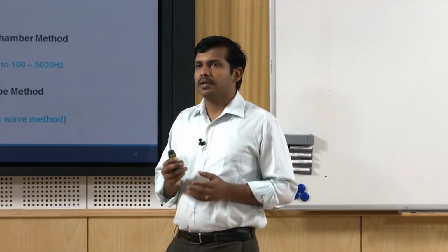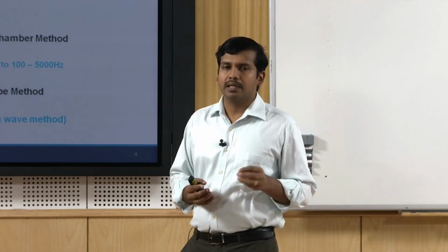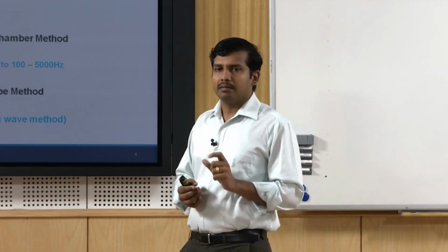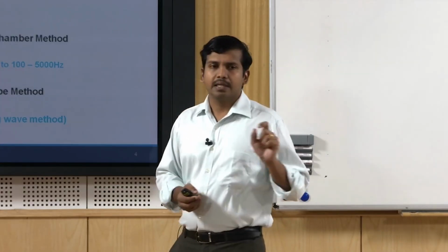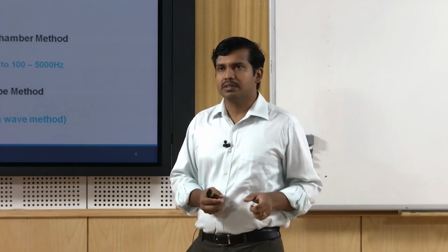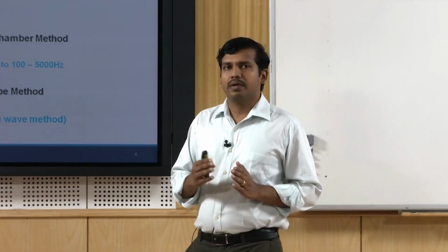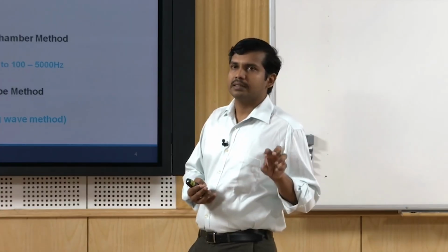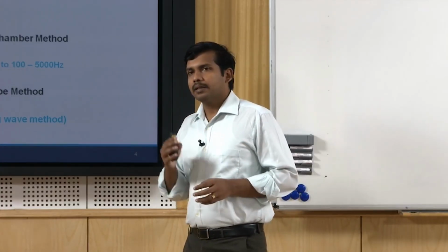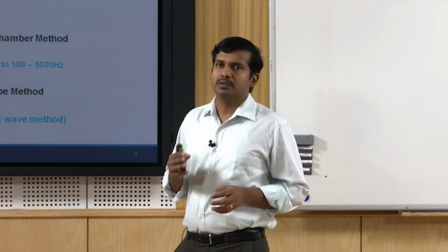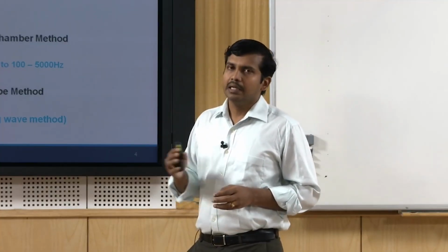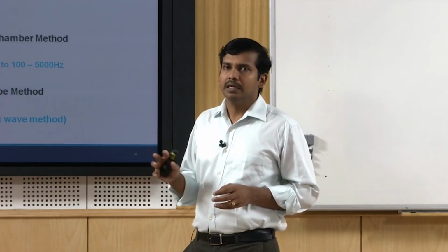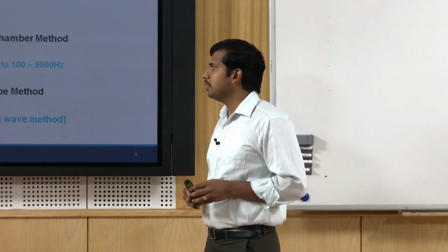So ideally when you select a material, if you want a real performance based selection, it is rather better to look at at least 3 specific absorption coefficients, that is absorption in the low frequency, something around 63 or 125 hertz or sometimes 250 hertz. Better is to look at 63 and 125 hertz. Then in the mid frequency range, that is around 1000 hertz, what is the absorption coefficient, and in the high frequency range something after 4000, say 8000 hertz is a good indicator of high frequency absorption.